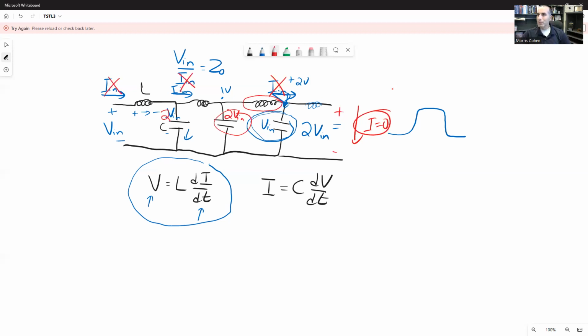And so this seems to have established something where this reflective wave was necessary in order to both satisfy the boundary conditions, where we have to have no current and only voltage, with the fact that the transmission line forced the V to I to be a certain ratio. This reflection was the only way to make everybody happy.